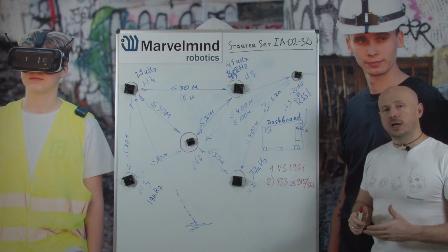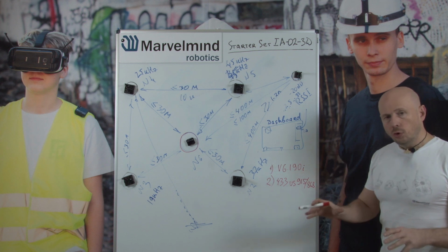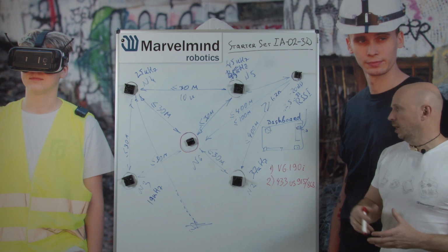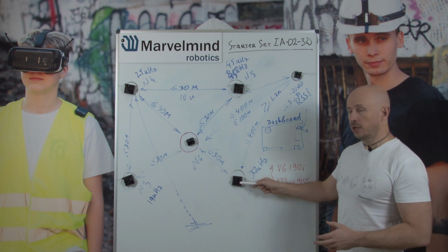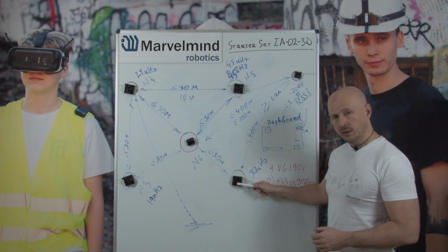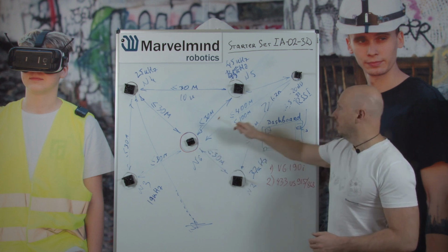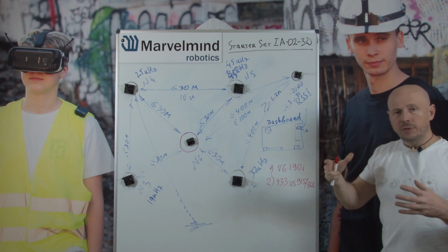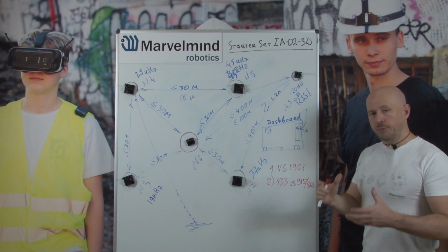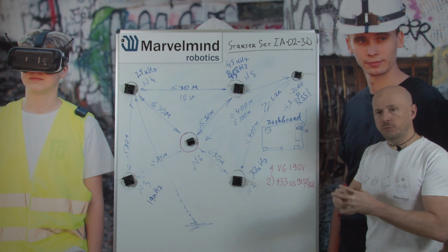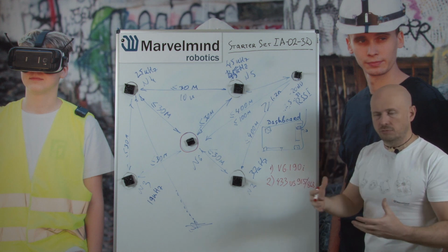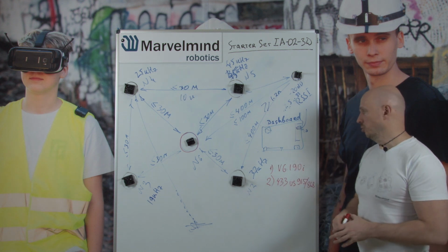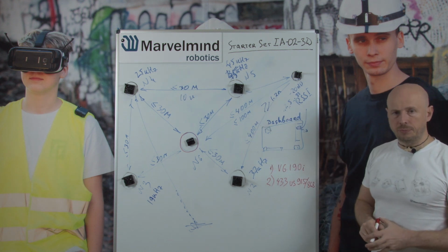As we always require, this is absolutely a must: always use the software from the same software pack. I hope by this time you already do this. It means that the software for the stationary beacon, the mobile beacon, and all other stationary beacons, the modem and the dashboard, all must come from the same software pack. Don't mix up the software between different software packs, because this is a very likely reason for all kinds of issues. So always from the same software pack.